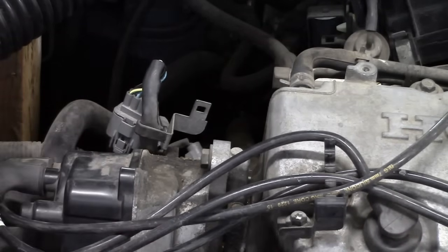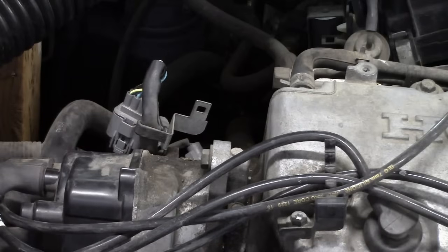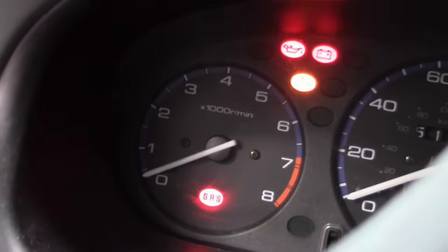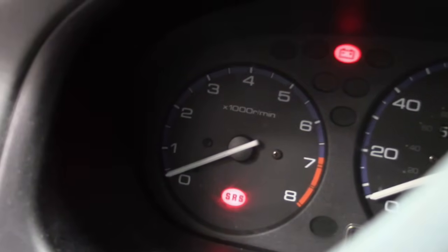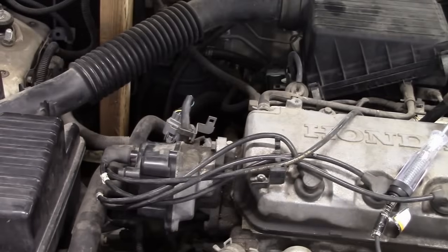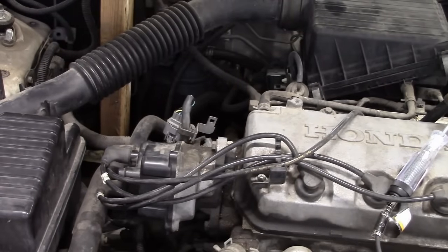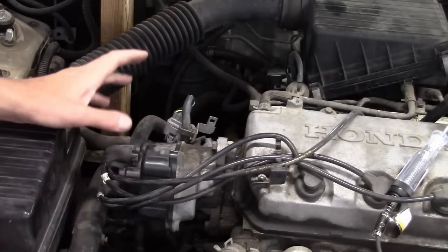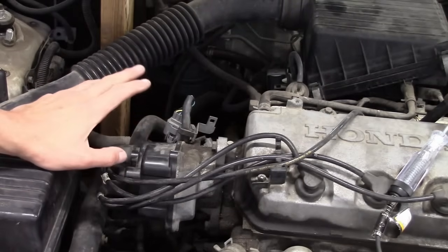What I did was, once I determined there was no spark, I went and looked at the tachometer on the dashboard while cranking and found that the tachometer didn't so much as budge. Might as well go ahead and show you that. You can see the tach doesn't even quiver or anything there. Now again, that is not a definitive test. There are plenty of cars where you do not see the tachometer move with cranking like that. So not 100%, but it was enough direction for me that I'm wondering if there's an issue with the cam, the crank sensor, one or both.